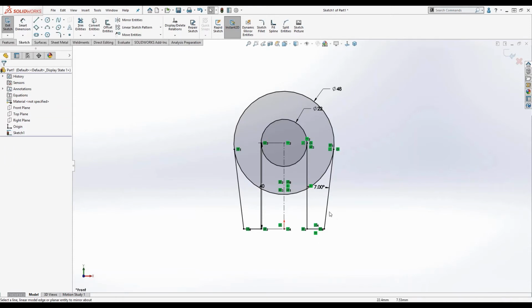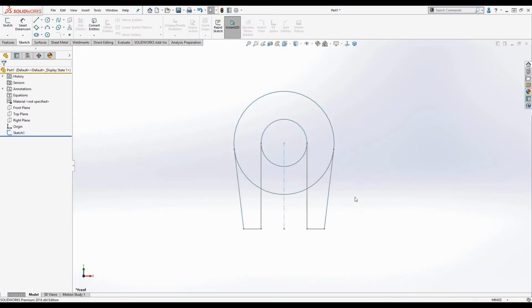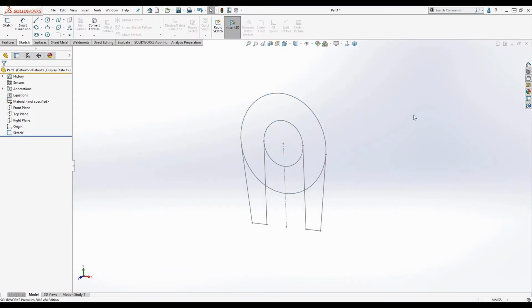I'm still within the sketch, so once again I can utilize that D key, bring that confirmation corner directly to me, and check out of my sketch, as opposed to having to go up to the corner every time and have this amount of mouse travel, right? So you're cutting down on this mouse travel every single time you do a feature or a sketch by utilizing that D key. So what's nice is that those come as defaults with the D key and the S key, and they're right next to each other, right? So S key for shortcuts, D key to accept. So you can just flip back and forth between those two.